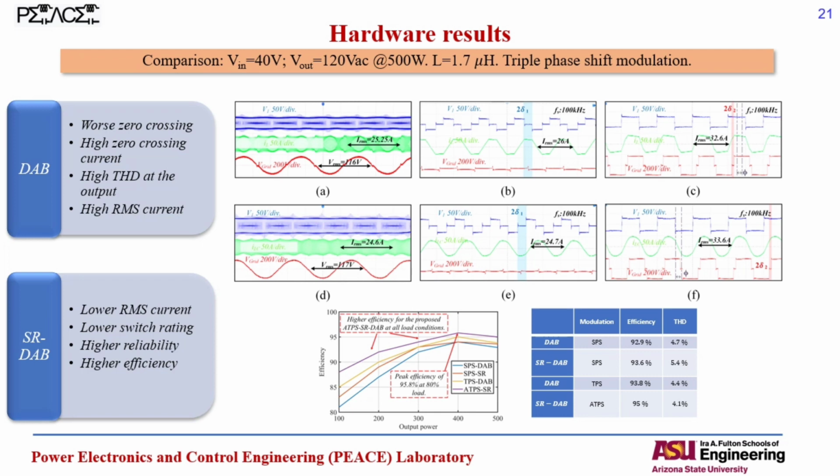Additionally, you can see that this ATPS, the advanced TPS modulation with the SR-DAB and with the optimized design, is showing a higher efficiency at all loads as opposed to the one that we had in the conventional DAB with the single inductance.